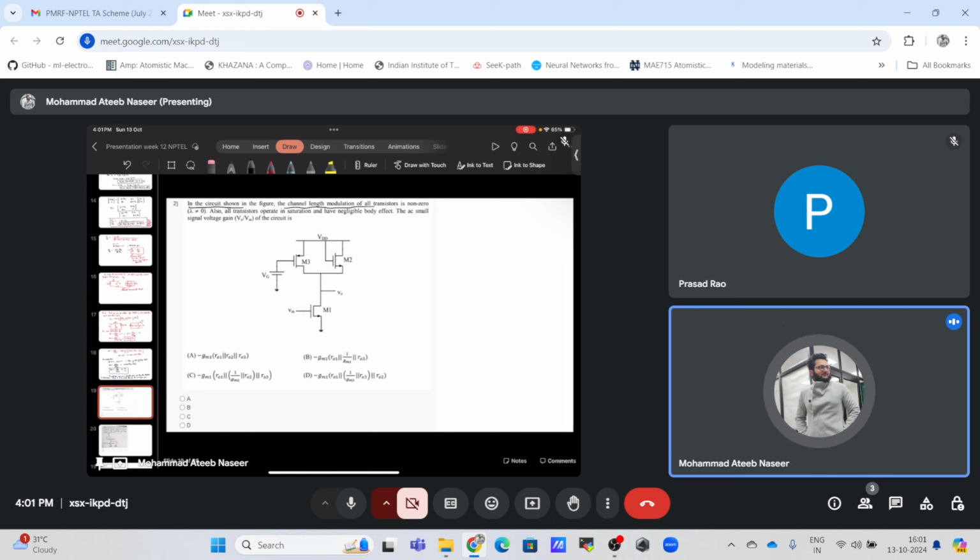Y22 is basically now the resistance which comes into the picture at the port between port 2 and 2 dash. You must have seen that the current does not saturate with the VDS, and as a result we will have some linear kind of increase in the current even after the saturation region.